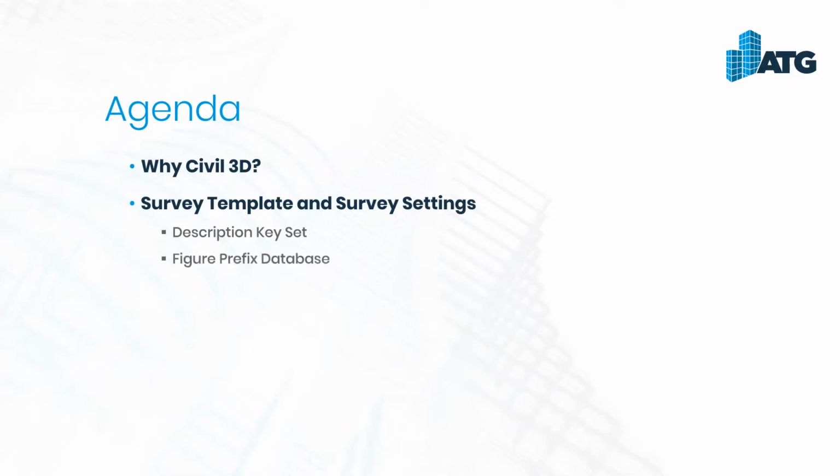From there, we've got our figure prefix database. From that list of points that get recognized on import, which ones are going to be used and connected by that automatic line? So we're going to be creating survey figures, and those codes are all prefixes, and that's why we get that name out of that. We're also going to talk about the linework code set.